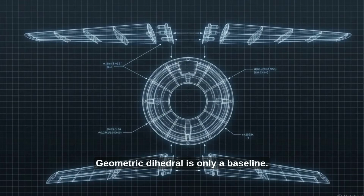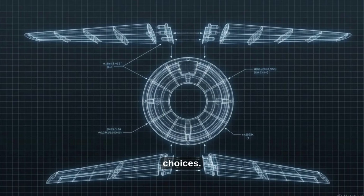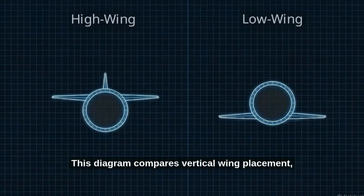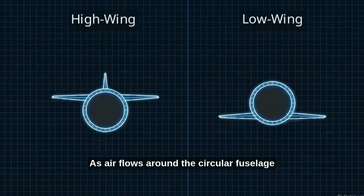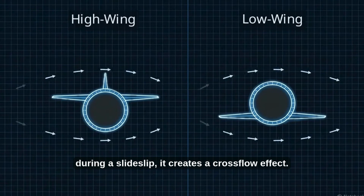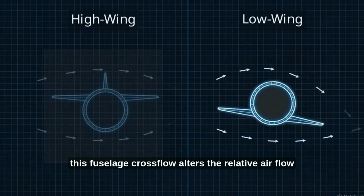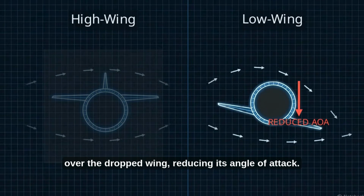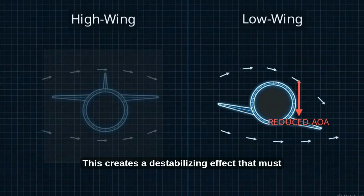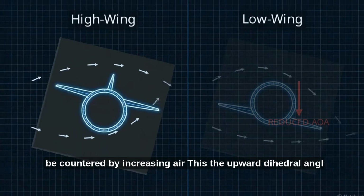Geometric dihedral is only a baseline. The total effective dihedral of an aircraft is heavily manipulated by secondary airframe configuration choices. This diagram compares vertical wing placement, which acts as a major contributor to lateral stability. As air flows around the circular fuselage during a sideslip, it creates a crossflow effect. On a low-wing design, this fuselage crossflow alters the relative airflow over the dropped wing, reducing its angle of attack. This creates a destabilizing effect that must be countered by increasing the upward dihedral angle.